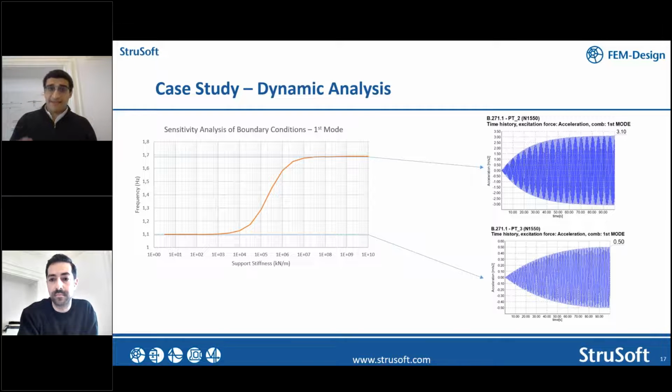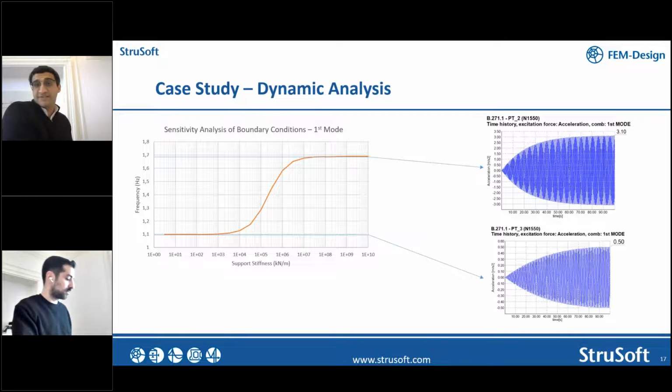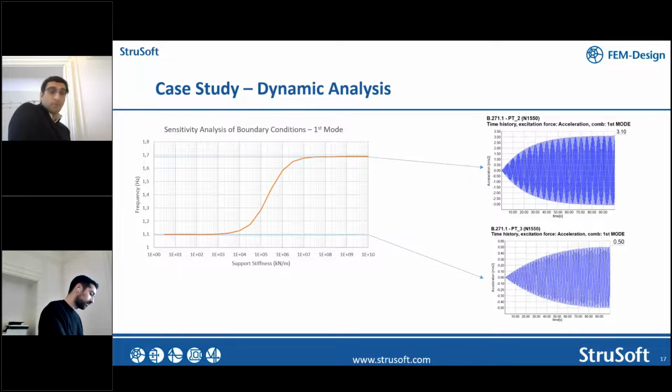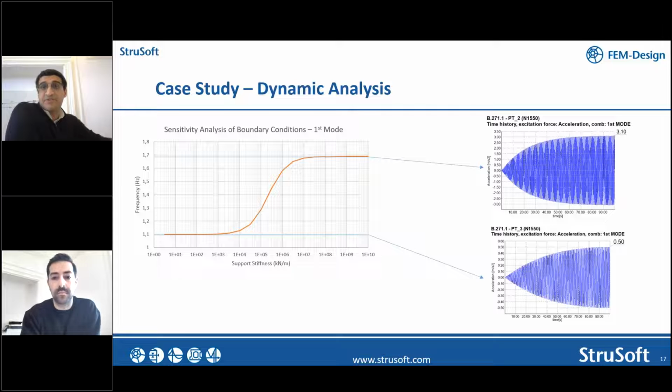So I would rather say that, depending on the construction solution that you have provided, your natural frequencies can be bounded. And as long as you can bound those natural frequencies, you have increased the information of the system. You know now more, such that you can make a decision on the dynamic assessment of your system itself. And this is due to the fact that, again, when you design for statics, the worst load case scenario will actually activate the boundary conditions.